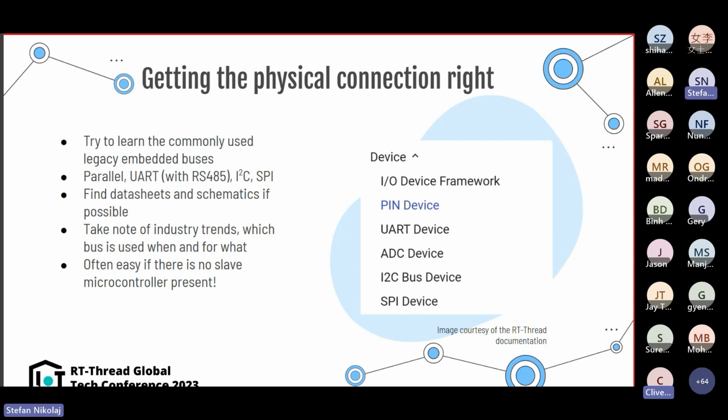Reverse engineering these protocols can be more challenging, but if you have the datasheet, the application notes, and you know the chips present on the board, it's likely that you can find some information online, the communication protocol in the datasheet itself. So as long as you have access to the datasheets for these chips, you can determine the communication protocol, unless you're dealing with a custom programmed slave microcontroller.